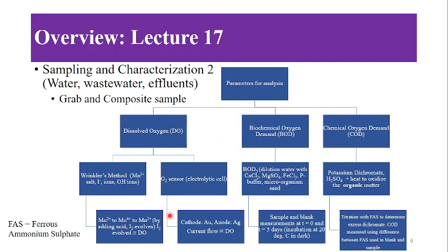Next is, in lecture 17, sampling and characterization for wastewater, water, and effluents was discussed. First we discussed grab and composite sampling. This is the same as grab and integrated sampling, but grab sampling is for low volumes, and composite sampling is for bigger volume and at frequent intervals.